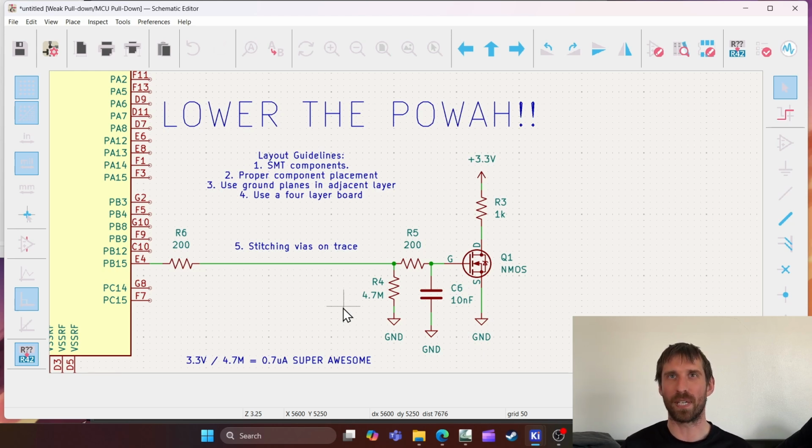I would have never dreamed that you could do something like this and potentially get away with it. I thought maybe 1 meg. 1 mega ohm might be pushing. I thought 100K might even be kind of aggressive, but with our modern techniques, it's probably okay. I had no idea we could even conceivably go up this high. So I kind of want to test this. So we'll see if I can get a board made and going on with something. What I probably would do is get some PWM going on right near these traces and see what can go on.